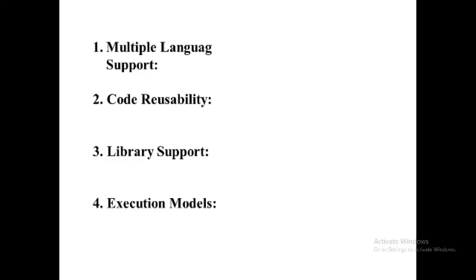Fourth, execution models. The general construction of the control algorithm includes the use of tasks, each of which can have one or more program POUs. A task is an independently schedulable software entity and can be assigned a cyclic rate of execution, can be event driven, or be triggered by specific system functions such as startup.